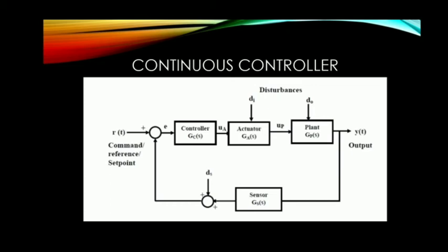It is for this reason that the choice of the feedback signals, that of the controller algorithm, such as P, PI or PID, the choice of the control loop structure, normal feedback loop, cascade loop or feed forward, as well as choice of the controller gains is extremely important for industrial machines and processes. Typically, the control configurations are well known for a given class of process. However, the choice of controller gains have to be made from time to time, since the plant operating characteristics changes with time. This is generally called controller tuning.